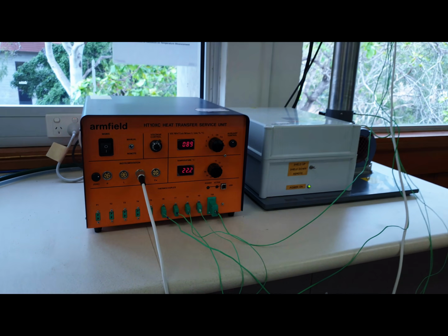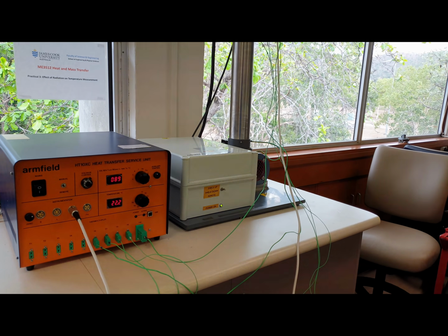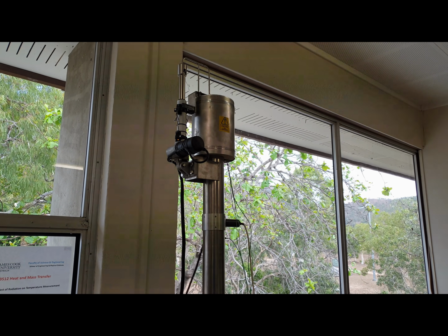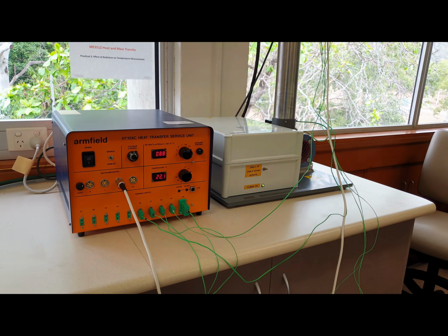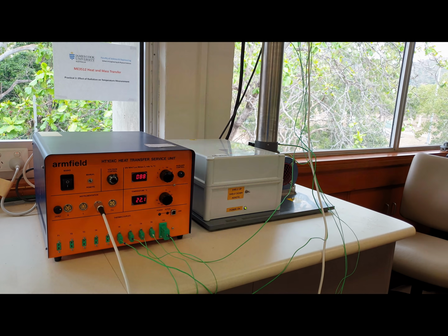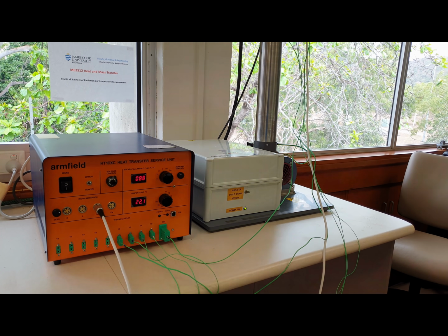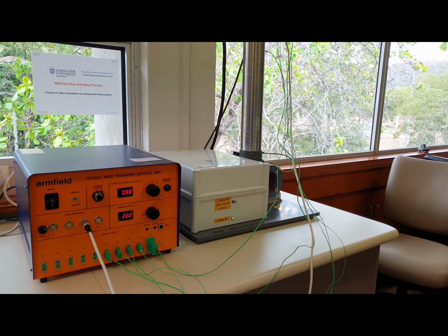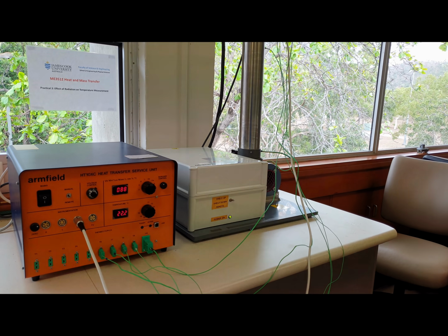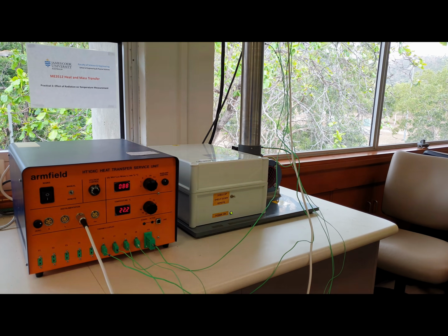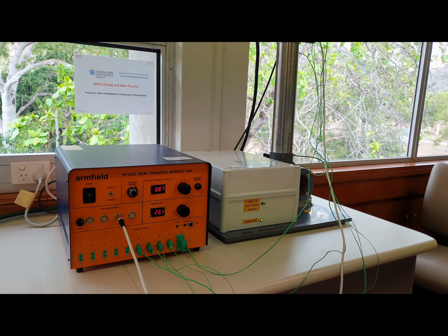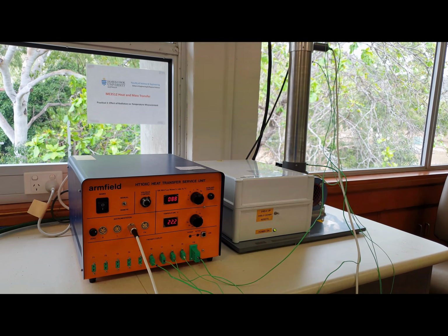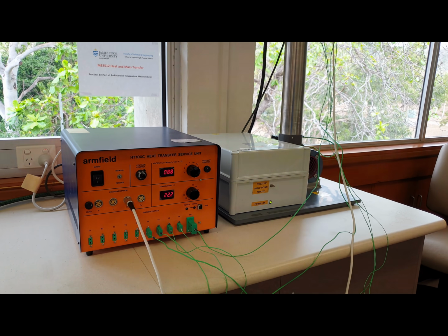So this is our case 4, which is we have forced convection and radiation. For this case, we can write an equation for the energy balance for the thermocouple bits. Why and how? Because we have both radiation and convection happening over the surface of the thermocouples, and we can evaluate the temperature of the thermocouples showing us. So let's see the details.